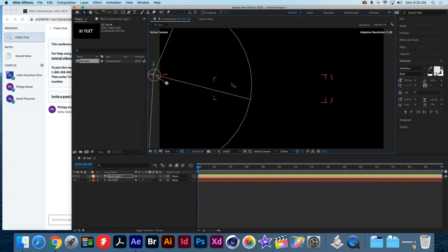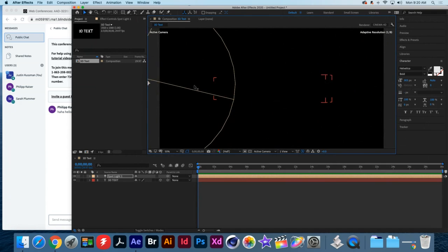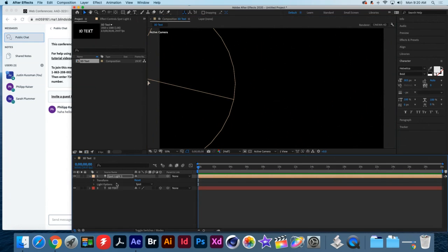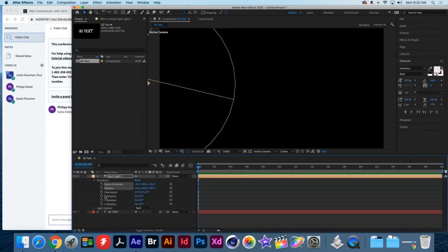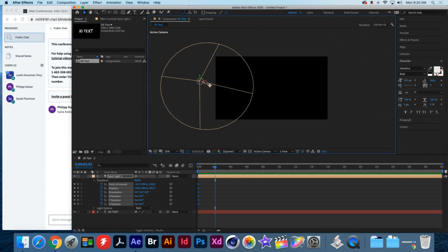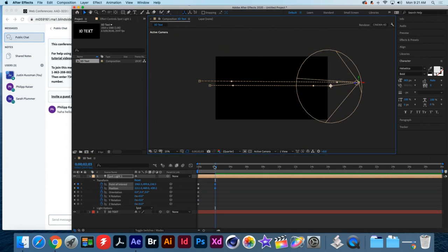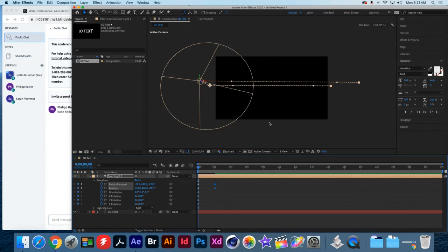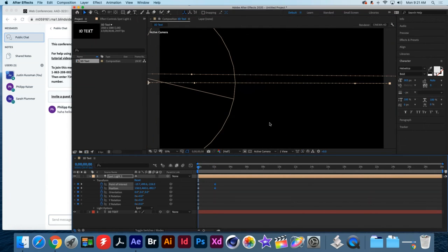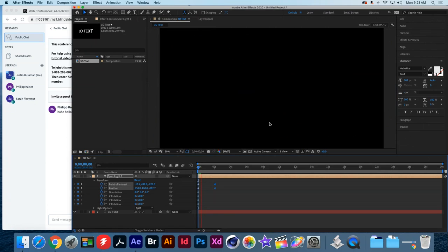If I wanted to just key in, drop down my little triangle here, go to my transforms, right? Turn on my transforms, drag my timeline. Let's say we take 2 seconds, and I can take this light and pass it across my text, okay, for an effect. That there, right out of the gate, is a pretty decent title effect. If I hit play on this, the light goes through and pans across my scene and illuminates my text, and the shadows all play interactively across there.